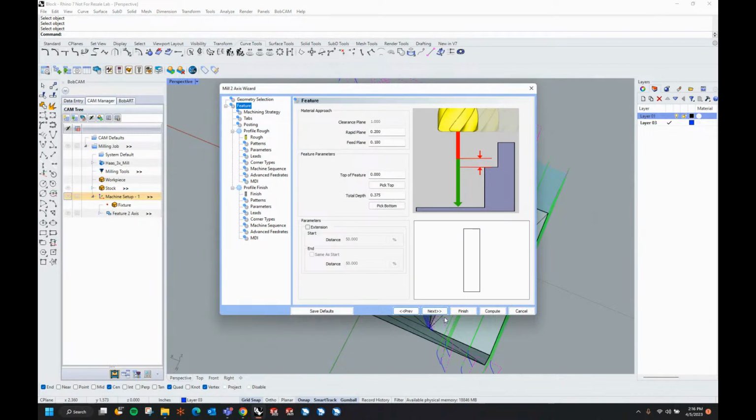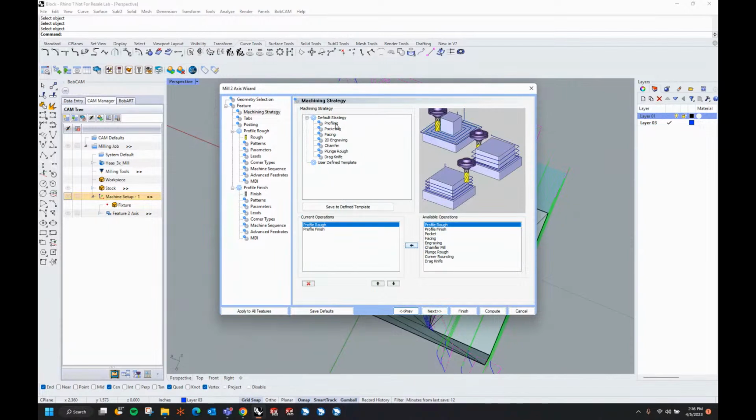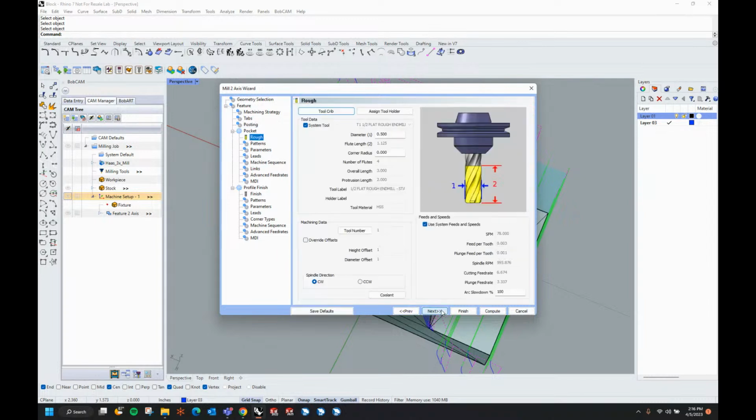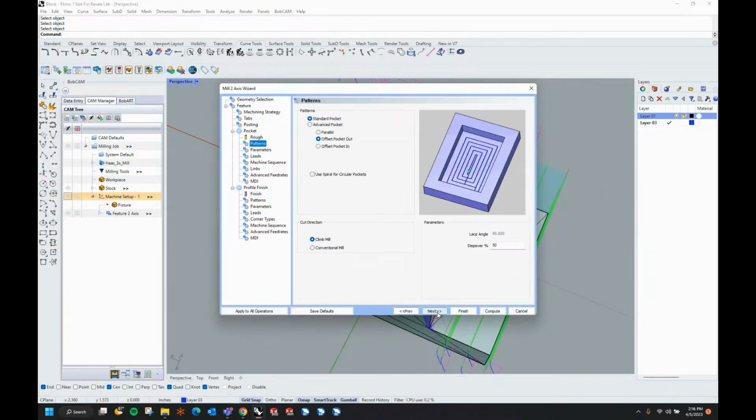So got 3/8 depth. And I am going to turn on extensions. And I'm going to go in with a smaller tool for this. So I'm going to do pocketing with the finish. So let's go ahead with a 1/4 inch. Now I'm going to use the adaptive roughing. So adaptive roughing, and we even have an article on this on our main website. It's the Understanding the Adaptive Machining, the Axial and Radial Chip Thinning. I definitely recommend downloading that if you're interested in learning more.